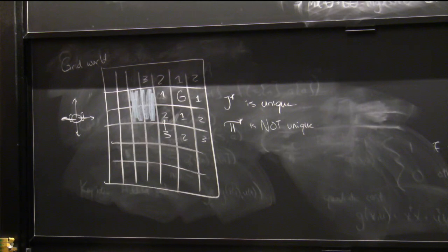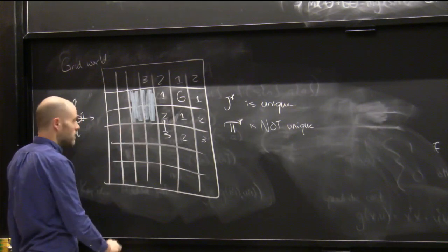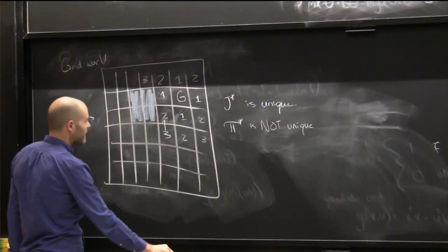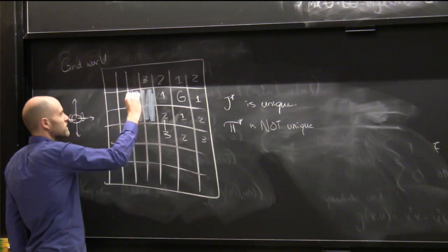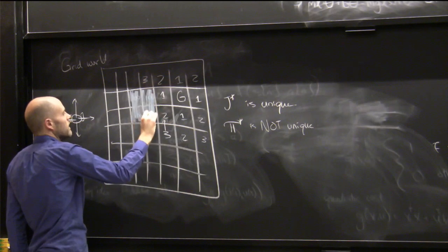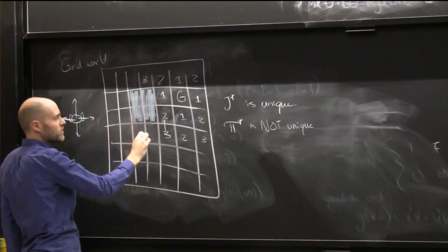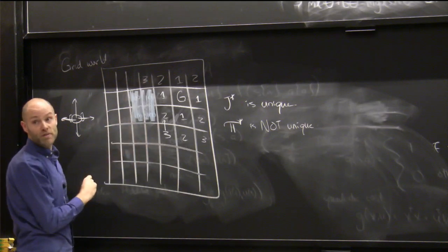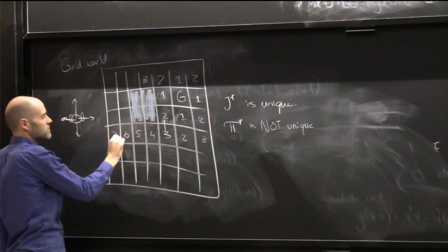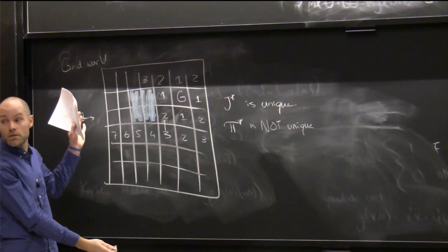Okay. If I wanted to add into my cost function something that says don't go in the pit, then you could just somehow rule that out and not put edges in there, or you could put just really high cost. You could say maybe my cost of being in here is 100, right? And then the DP algorithm will never choose to step inside that, so it'll work its way right around it, right? And eventually you'll have a map across the entire grid.